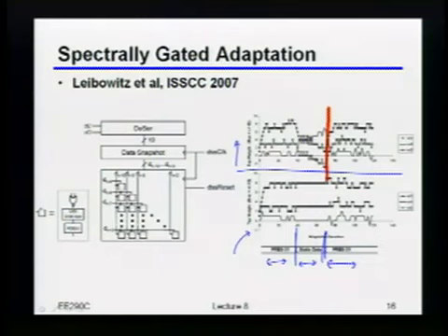Yeah. I was wondering, can you just XOR your sequence with a known long pseudo-random sequence to avoid this problem? OK, that's a great question. So what Igor was saying was, can you just take your sequence and XOR it with some known random sequence, and then hopefully that known random sequence is different than your data, and so you should guarantee that things are sufficiently random. That's indeed something very common. That's what's called scrambling. That's a very, very common technique, both in Ethernet, and even wireless systems. Indeed, that's something that is fairly commonly applied.